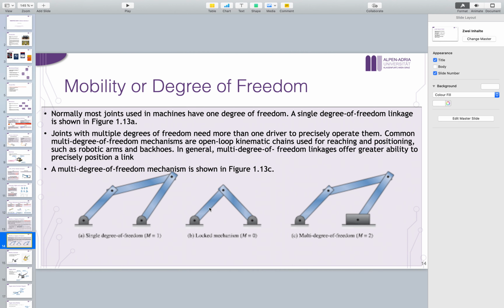Now if I look at this mechanism in the beginning, and look at how many joints I have here: 1, right, 2, 3, 4. 4 is basically, we will see now if this rotates or not. There's a question about mobility, but let's assume there is a rotation here. 4. 5 is a slide.